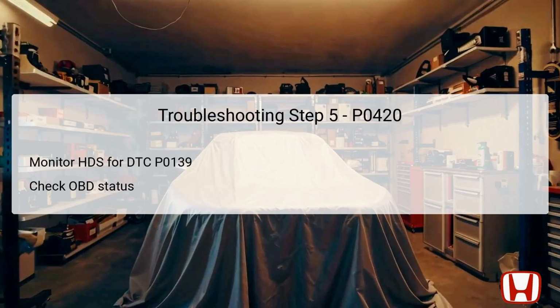If the status shows passed, the vehicle may be functioning properly, but if it does not, follow the confirmation steps for DTC P0139 to address the problem. Solving this code will likely clarify the root cause of the initial P0420 code and may involve further steps like inspecting the wiring or replacing the secondary HO2S.